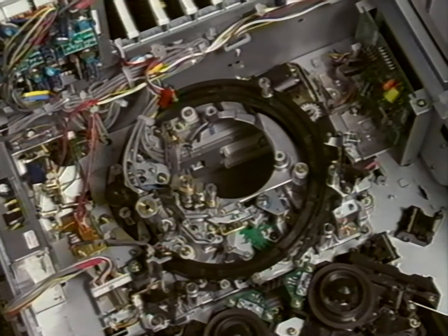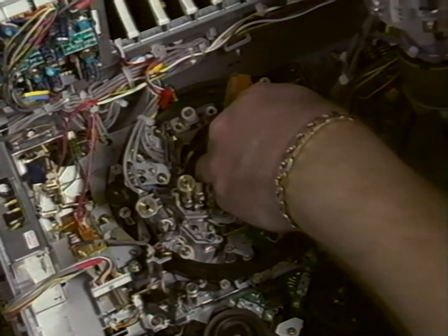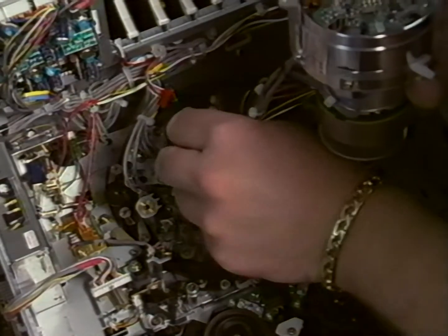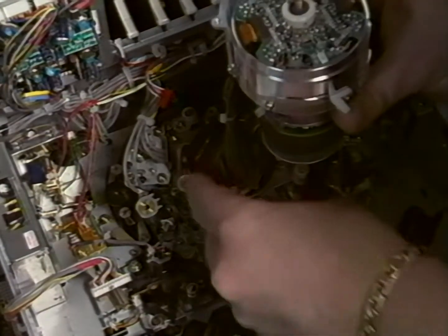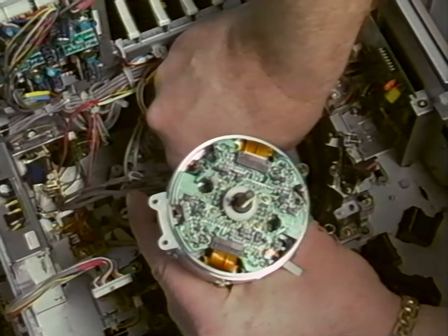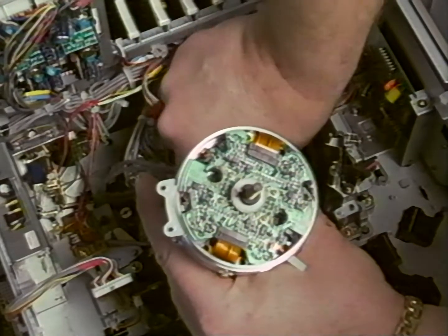To install the new drum assembly, place the 6 wires back through the hole in the chassis as shown, and then take the 4 wires that go to the RP29 boards and pull them underneath the threading ring to the back of the mechanical chassis. Now lower the drum into the hole of the chassis.